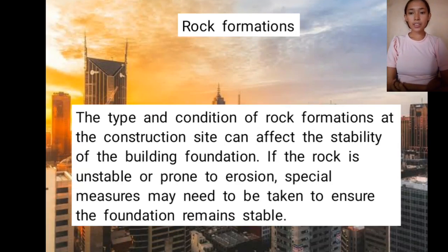Lastly is rock formations. The type and condition of rock formations at the construction site can affect the stability of the building foundation. If the rock is unstable or prone to erosion, special measures may need to be taken to ensure the foundations remain stable.